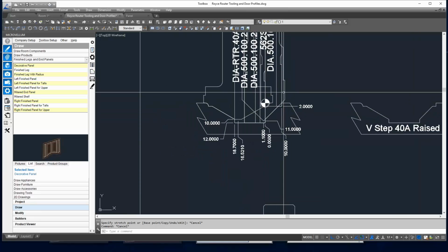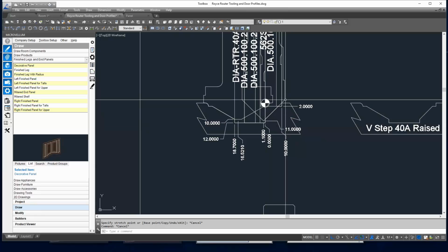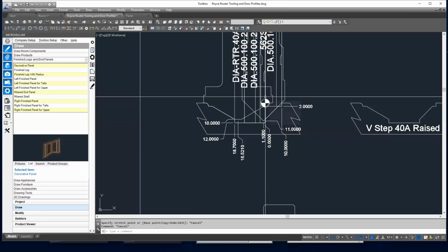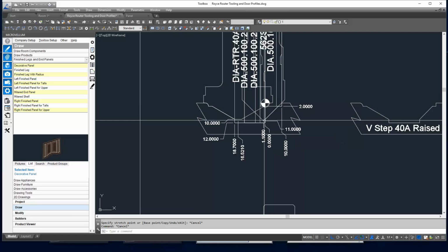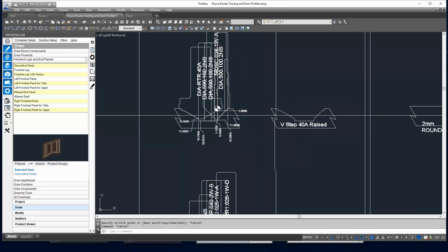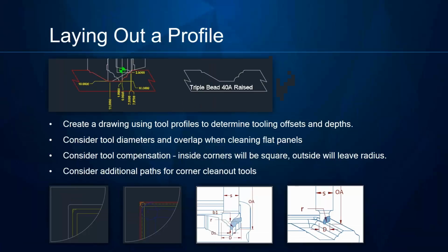So when I'm thinking about that, I need to think about the size of my rail, where I want to call the 0. So when I specify a 2-inch rail width, I've said that the bottom or the front edge of what would be the stick profile, that would be where I would run, and so I'm going to measure my dimensions off of that. And so you can adjust that as you like, set up your profiles as you need there.